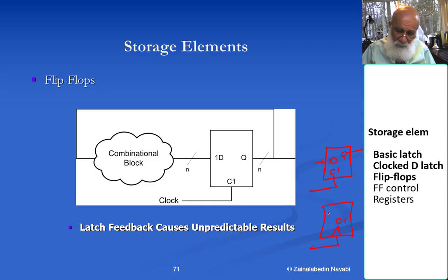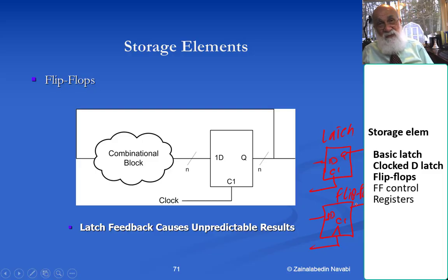Still, I'm showing that the D input depends on the rising edge of the clock. This is a latch. This is a flip-flop. A flip-flop stores something and is not transparent. The latch stores something, but it is transparent.